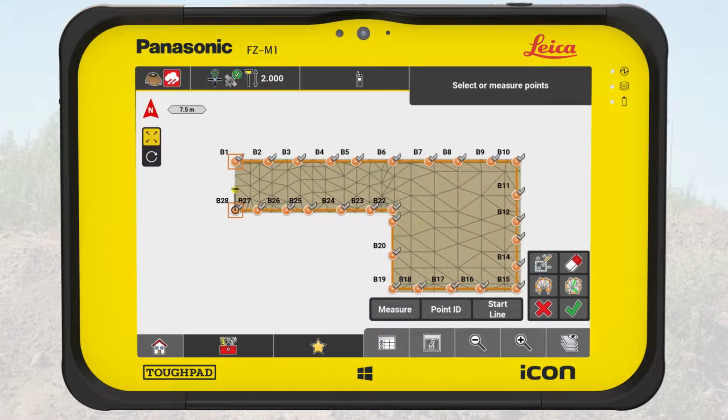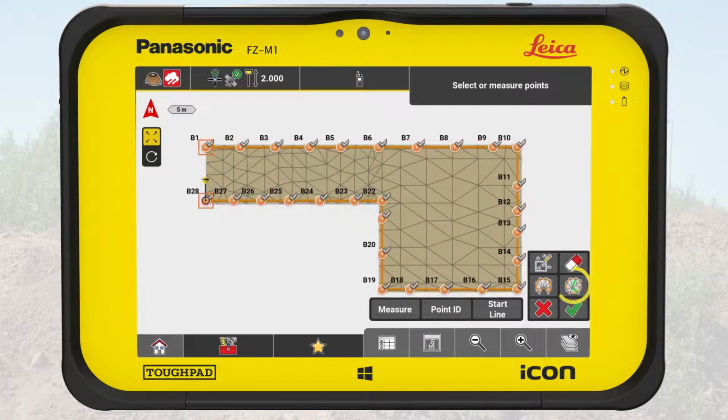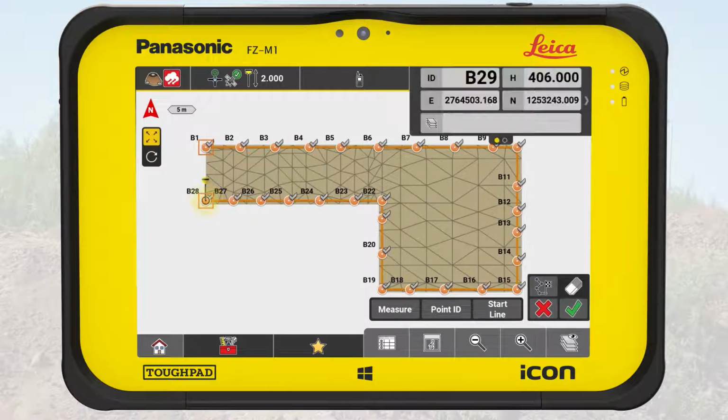As the next step, we define the break lines from the edge points to the 2 sewage covers. We imagine splitting the parking lot into 2 rectangles. In each of them, in the middle, a sewage is built. We tap on the Break Lines button from the toolbar. We select one edge point, measure the sewage cover's middle point, and select the other edge point.